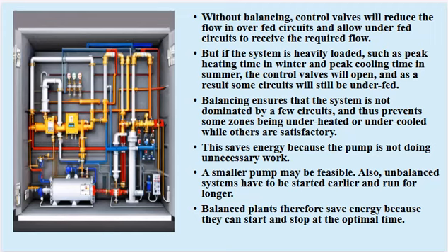Hydronic balancing ensures the system is evenly distributed, preventing some zones from being underheated or undercooled while others remain comfortable. This balance not only optimizes the indoor climate but also saves energy by reducing the pump's workload. With a balanced system, a smaller pump may be sufficient, and the system won't need to start earlier or run longer, as is the case with unbalanced systems.